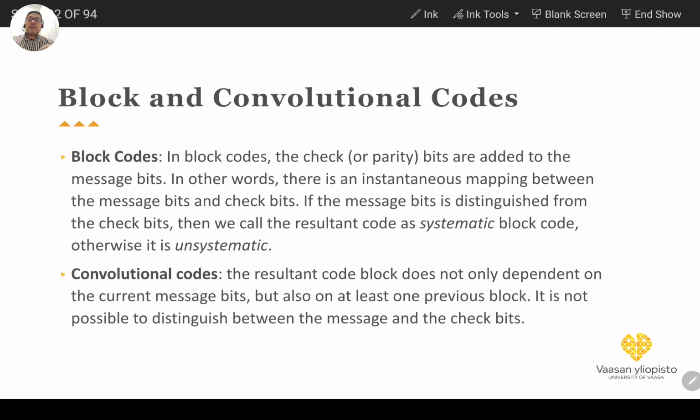in digital communication. It has many different algorithms, and it has already reached very advanced levels. For example, with a very small signal to noise ratio or Eb over N0, using this kind of convolutional code, we can reach very good performance, as it is known from the channel limit that we need Eb over N0 to be at least 0.7 in order to detect the message correctly. And with these turbo codes, for example, we are quite close to that limit.